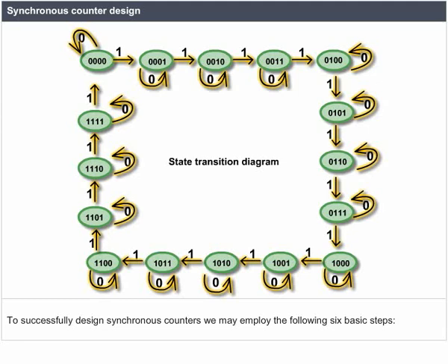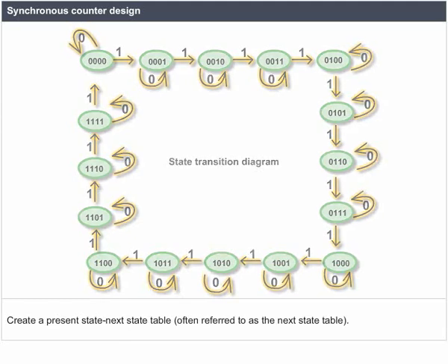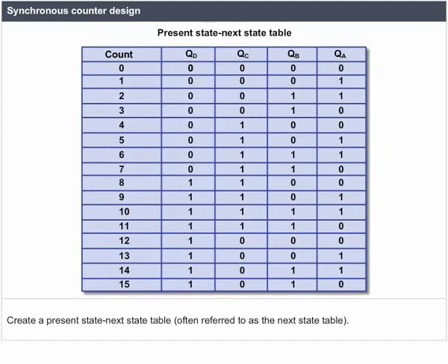Synchronous counter design. To successfully design synchronous counters, we may employ the following 6 basic steps. Create the state transition diagram. Create a present state next state table, often referred to as the next state table.